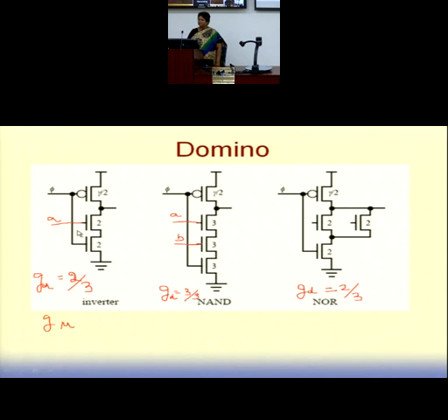Okay, and then it's very simple. G, if you look at G pre-charge, pre-charge is same for all. And no input is going to pre-charge. For pre-charge operation, nothing is going to the pull-up block. Inputs are getting retained only in the pull-down.